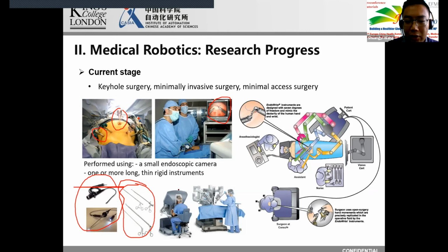This shows the configuration of the Da Vinci system, which has an important concept called master-slave, where the surgeon works at the console, which is the master, and the robot is in close contact with the patient, which we call the slave. Because of this configuration, clinicians don't need to stand up, and they can control multiple tools within these small areas. Because of the robotic arm, they can also reach higher positions and get rid of shaking movement, which are also benefits of using this robot.